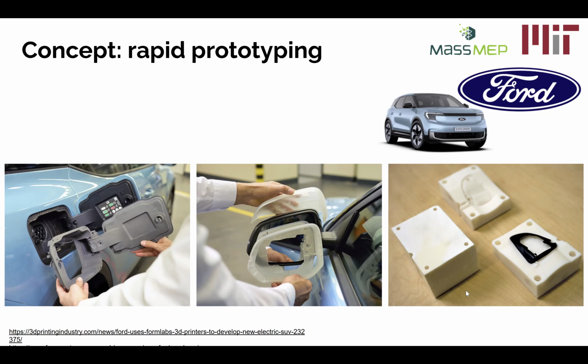But also, as you can see in the third picture, it was used for crash tests. When you run a crash test of an automotive vehicle, you need to use not only the same material, but also the same manufacturing method for the test to be acceptable. So when some components were meant to be manufactured using plastic injection molding, it would have been too expensive to manufacture a steel mold just for a few dozen components for the test, especially because we talk about rapid iteration here.